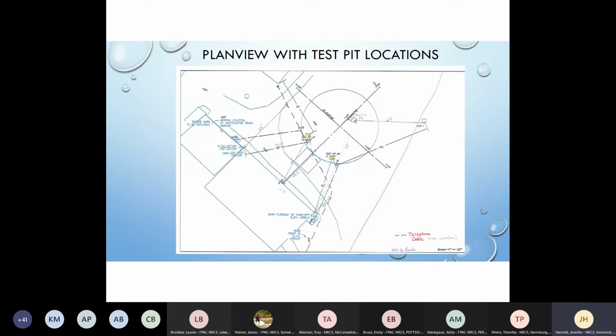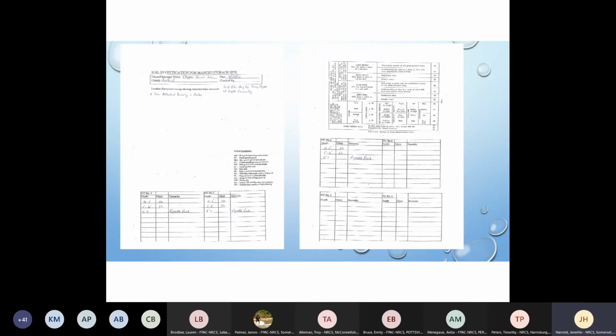It's good for the planning, knowing if we have to have rock or if there's going to be a lot of water. We need a 6-inch perforated tile around as the foundation drain versus a 4-inch, plus cost if there's rock excavation. So they did a really nice job. They had 3 test pits, the logging information here, and with these we're looking for, like I said, water, rock. Is the rock rippable or not?